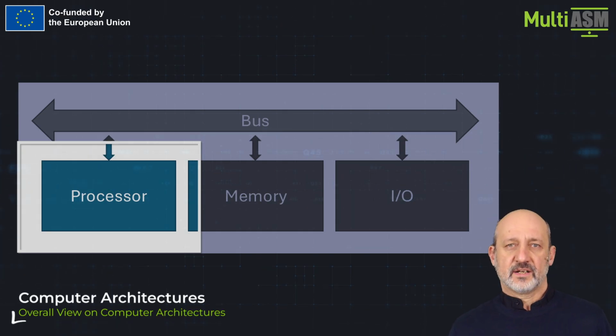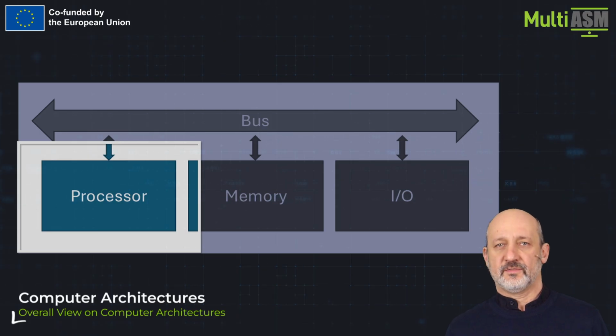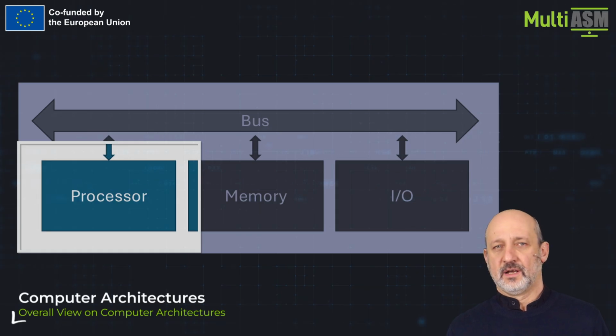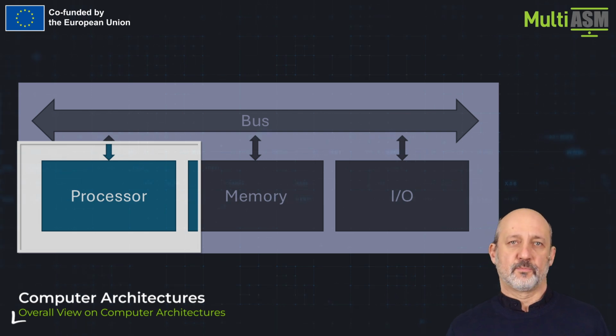A processor is characterized by its main parameters: the frequency of operation and class. Frequency is very important information which tells the user how many operations can be executed in a time domain. To have the detailed information of a real number of instructions per second, it must be combined with the average number of clock pulses required to execute an instruction. Older processors needed a few or even a dozen clock pulses per single instruction. Modern machines, thanks to parallel execution, can achieve impressive results of a few instructions per single cycle.